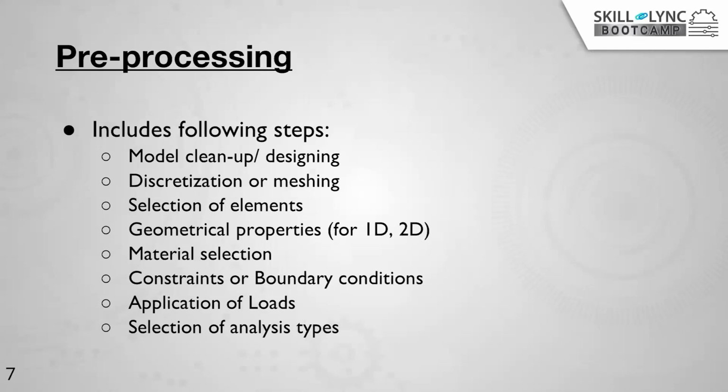Now selection of analysis type. So basically you want to carry out crash testing of the car, right? So for that, the most relevant analysis is explicit analysis. Okay. Softwares which can be Radioss, LS-DYNA, or Abaqus Explicit. So you can use that, right, as a solver. Okay. So all these things come under pre-processing.